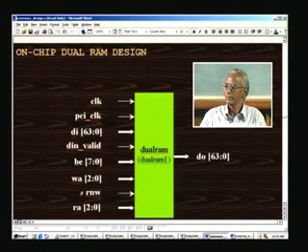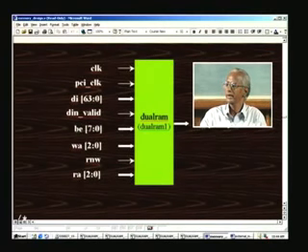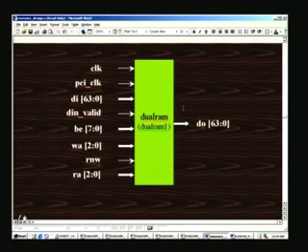into a RAM, we will change this value so that the 2 RAMs interchange their roles. What was written into will now be read, and you need a read address, and once again it is 8 locations read, that is what we are seeing here. As I mentioned, there is a special access in this RAM which is quite different from the conventional. In fact, the whole design is totally unconventional, and that special feature is, as you write, you will be writing along the row. The organization is 8 into 64, so all along the row you will be writing, but while reading you will have to read it vertically.